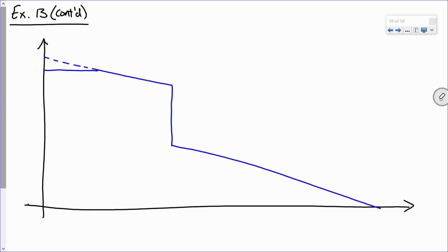So technically, the shear diagram extends all the way up to 68 kips. So this is my shear in kips, and this is my x distance in inches, right? All right. Now, technically, this extends all the way up to 68 inches. However, what we're allowed to use for design is this 61.333, and that's VU star. Okay? Maybe I'll erase that out a little bit, do that a little better.